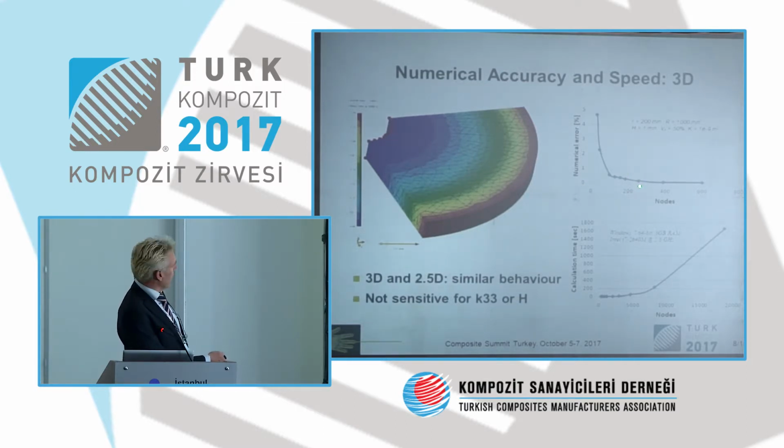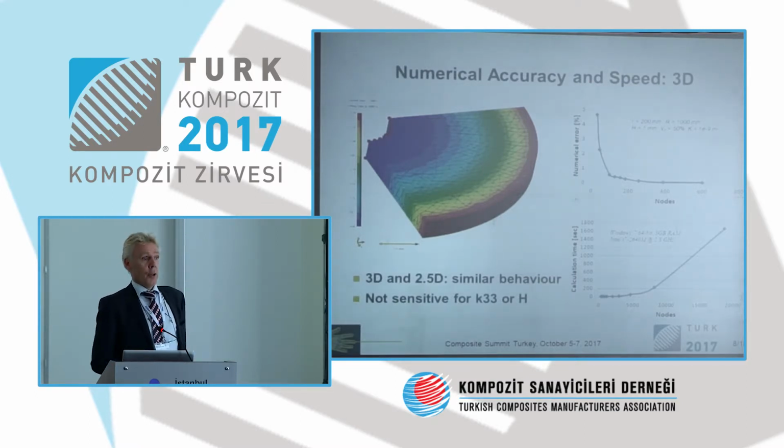And you can see here that with 200 nodes, that's this point here, we have less than 0.5% numerical error. If your criterion is 1% numerical error, well, you're here. So that means about 100 elements. And numerically, you're already very accurate. You will need more elements to get sufficient resolution to see what the flow actually does. So bottom line is, you don't need to worry about accuracy.